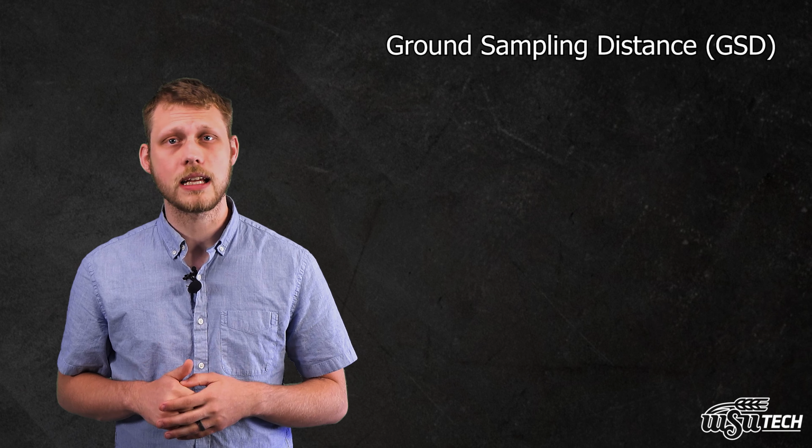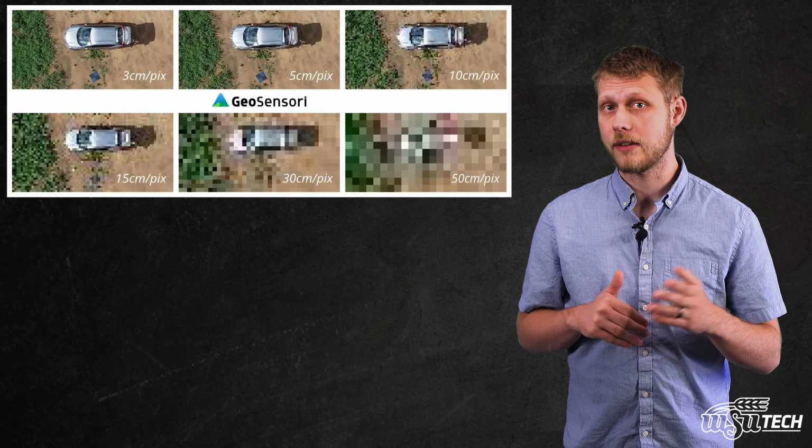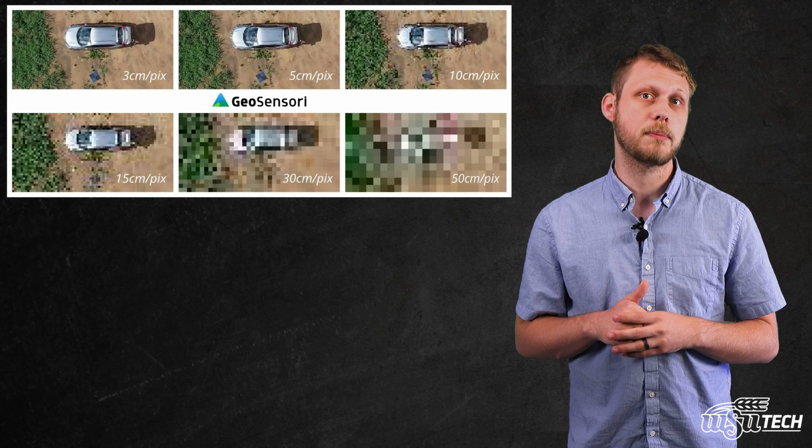Here's something a lot of new pilots miss. GSD stands for Ground Sampling Distance. That's how much ground is covered by 1 pixel in your image. The lower the GSD, the more detail you capture. A GSD of 2 centimeters means you can see small surface cracks. At 5 centimeters, those details disappear.